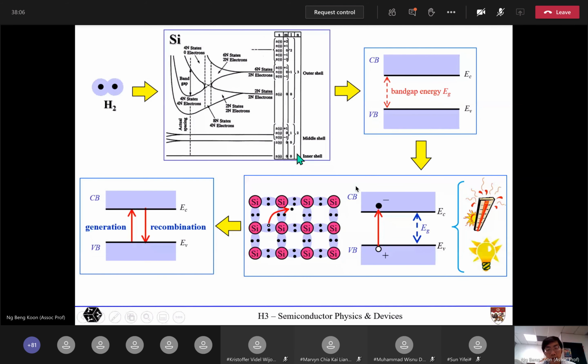Okay, so other than this process where electrons and holes are being created, that's called a generation process because they generate free carriers. In a semiconductor, you also have another countering process called the recombination process that would cancel out the electrons and holes. Physically, you can think of it as an electron moving in a semiconductor when it's free to move, right? And if it sees a hole, there's a chance that it could go back to the hole and complete the bonding, right? Complete the valence bonding.